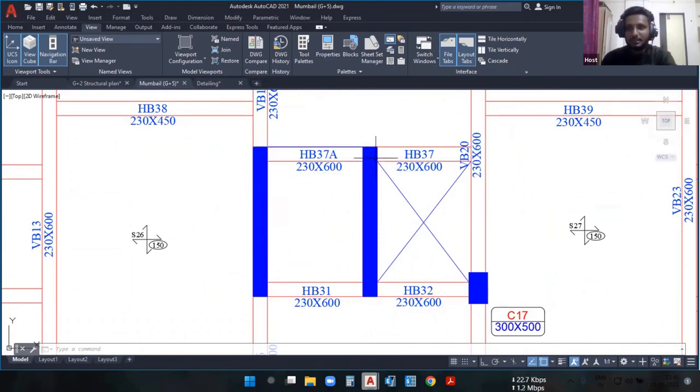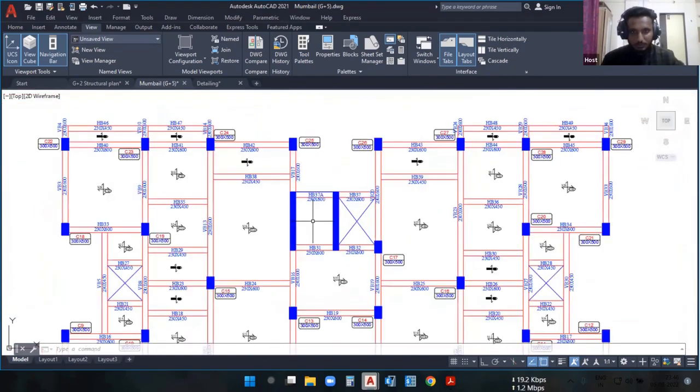The shear wall is basically exactly similar to the column, but it has a different purpose. A column can only resist the compressive forces which act in a vertical direction, like in the Z direction. But the advantage of a shear wall is that it provides more stability against the seismic forces. The shear wall also provides stability to the building against the gravity forces acting in the Z direction, and also stability to the RC building under the action of horizontal forces. We'll also talk in more detail about the difference between columns and shear walls once we get to this course.